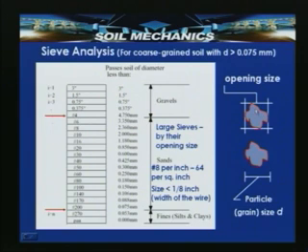In this slide we see a mesh with the opening size indicated by a sieve size, which gives particle size D, which represents the equivalent diameter. Basically, the soil particle cannot be of any regular shape, it can be of any shape, but finally it is given in terms of the equivalent mesh size of the sieve.